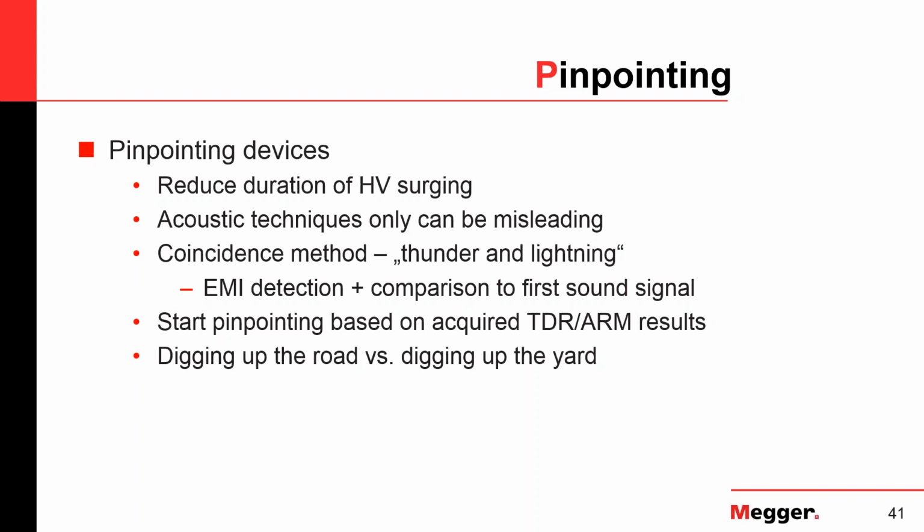And for that purpose, you can get to the fault fairly quickly. And since these coincidence devices are based on the first sound, they also don't get fooled by conduits, because the ends of the conduit is typically where the biggest noise is that a human would run to, but the computer cannot be tricked with an algorithm like that.